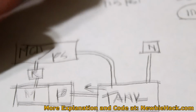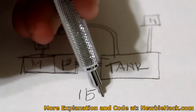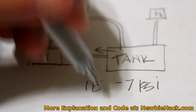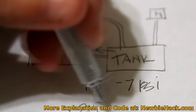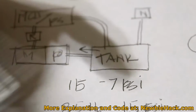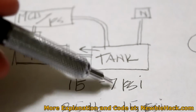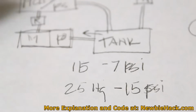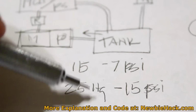When the pressure goes above 15 inches of mercury, or approximately -7 psi, the motor will turn on. If the motor has reached 25 inches of mercury, which is approximately -15 psi, and this is relative to the atmospheric pressure around it, so it's not really a negative psi, it's a negative psi relative to the atmosphere outside of the tank. And when the tank reaches 25 inches of mercury, the motor will turn off.